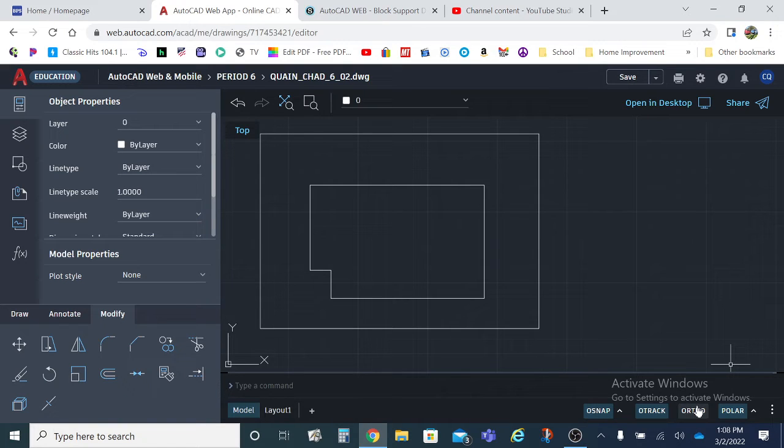One thing that I don't remember if I talked to you guys about when you're using the trim command is you can hold the shift key down while you're in trim, and you can do something called a flip flop. What flip flop does is it allows you to take the trim command and turn it into the extend command. You can also do the same thing if you're in the extend command: you can use flip flop by holding the shift key and turn it into trim. It's a pretty nice little feature for when you want to do something real quick and you don't want to get out of a command to go back into a command.